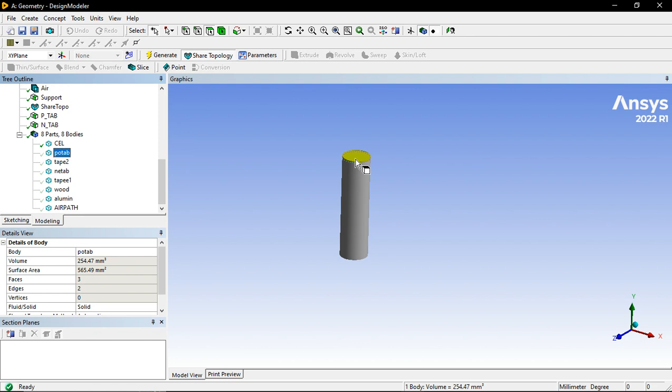So to electrically insulate this metallic bus bar, I have used polyamide tape to electrically insulate the system, and let the system be thermally conductive, because this polyamide tape, this Kapton tape, is thermally conductive while being electrically insulating.